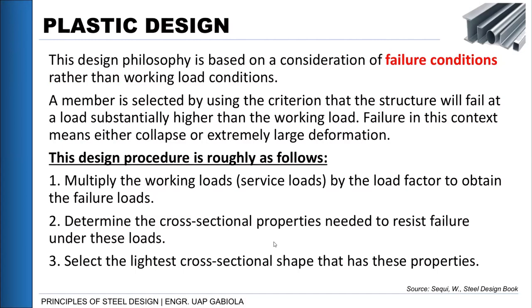In steel design, plastic design is also used because from what we have learned, steel is a very ductile material. So even though it is already experiencing deformation, its strength is still usable. So it still possesses some strength. And then according to the graph, after its plastic behavior, our material will still attain its ultimate strength. That is why some say that plastic design is much better than the other two design philosophies.